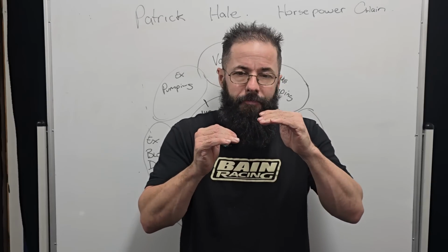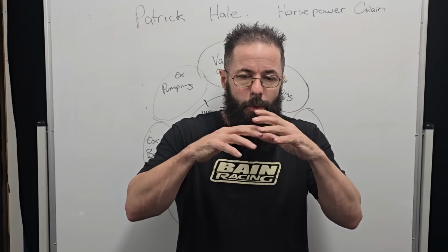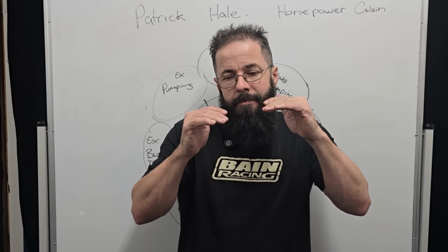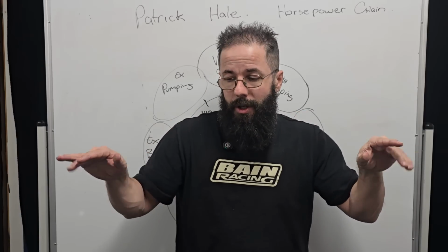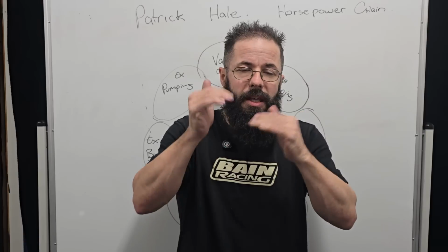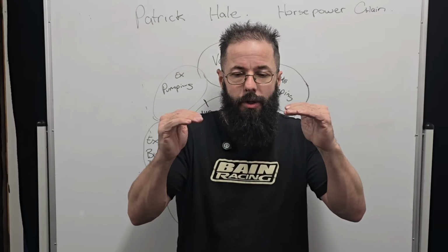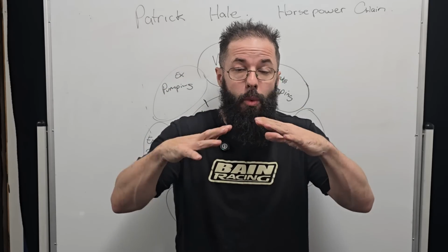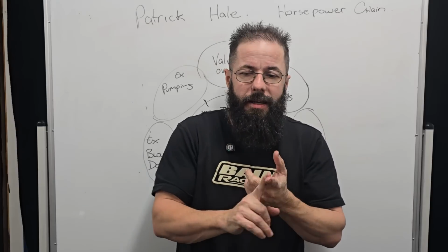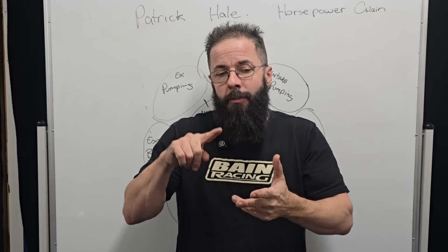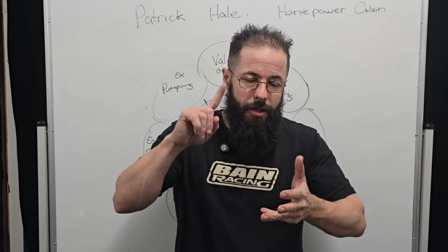And even the nose radius we were broadening. Sometimes when you look at area under the lobe, if you include a lot of that rubbish, the area won't change. So I tend to look at my area at 50, and we're actually getting more area under the lobe as well. And these things were making better horsepower. We had better dynamic compression.